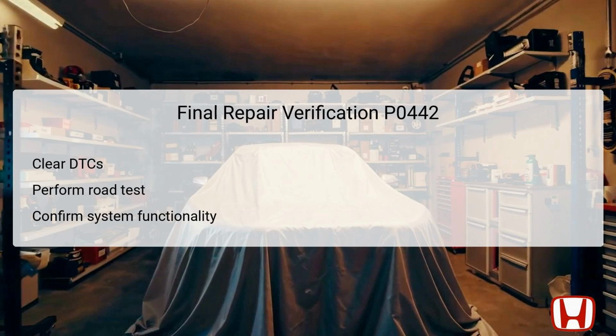Once all necessary repairs or replacements have been made per the troubleshooting steps, it's critical to perform a final verification of the repair process. Start by clearing all DTCs using the HDS to eliminate any previous fault codes that might interfere with new diagnostics. After clearing the codes, conduct a road test to monitor the vehicle's performance and confirm that the check engine light remains off.